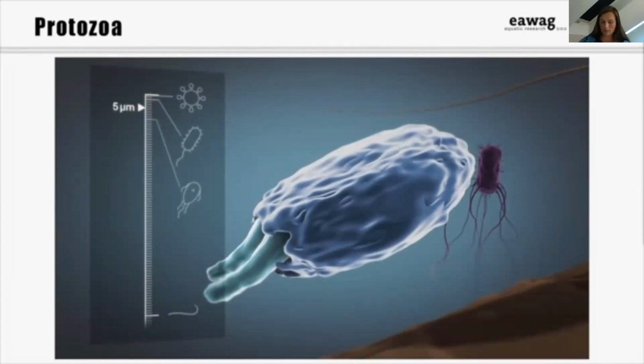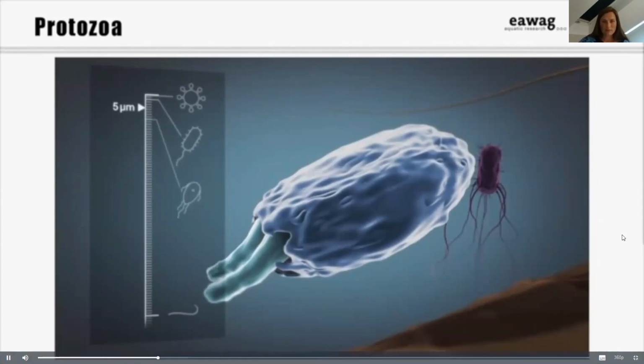The first human cases of crypto were reported in 1976, and the disease became infamous in 1993 when an outbreak occurred in the northern U.S. city of Milwaukee. Cryptosporidium overwhelmed the treatment plant's filtration system, and chlorine has no effect on crypto. Over 2 weeks, 400,000 people became ill, and over 100 deaths were caused, mainly in people with compromised immune systems.